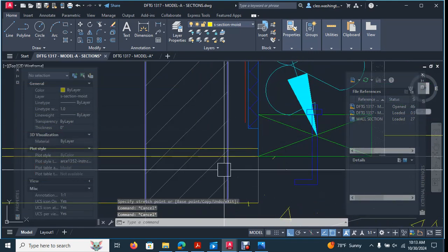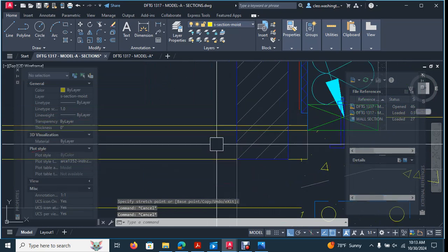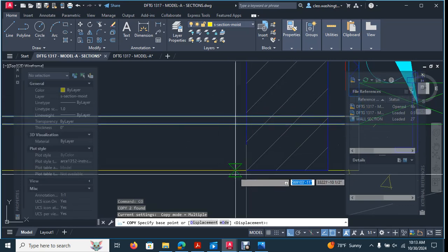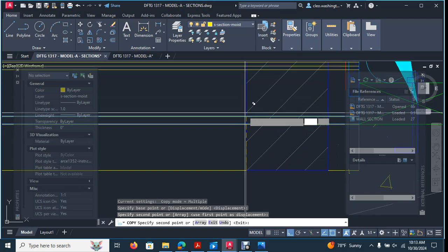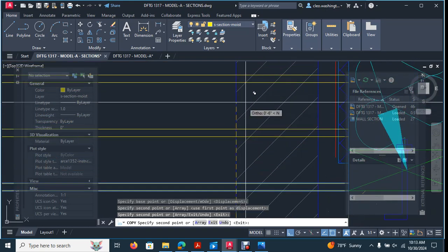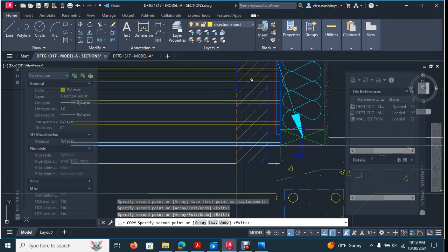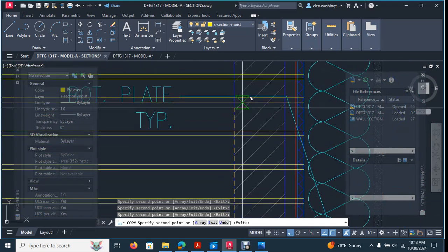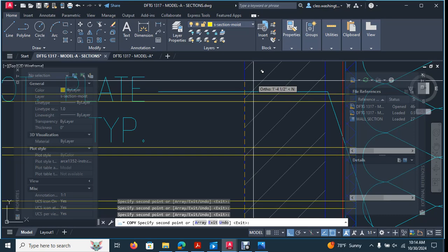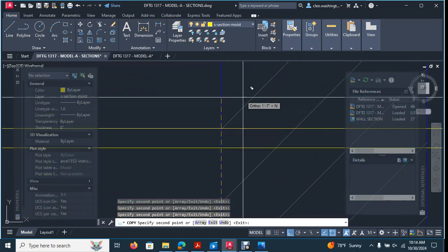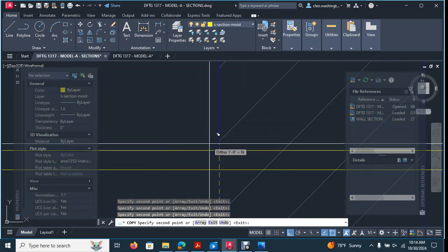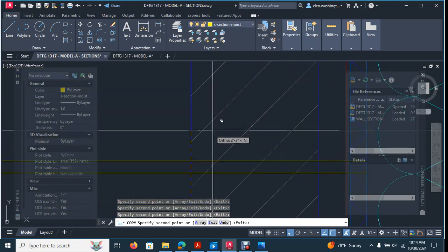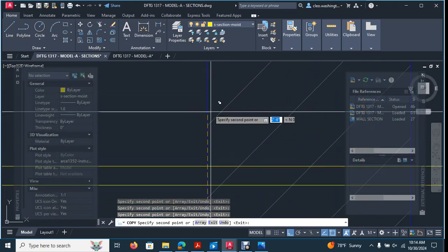All right. So now what you're going to do is copy these two lines. And you always copy up to the top line. And what I'm doing is we're actually going to show how the brick is coursing dimensions, okay? I have to make sure, because what happens is you don't want to get to a point to where you have to have the contractor cut brick. So you need to make sure all of your brick dimensions course. It needs to course vertically. It also needs to course horizontally.